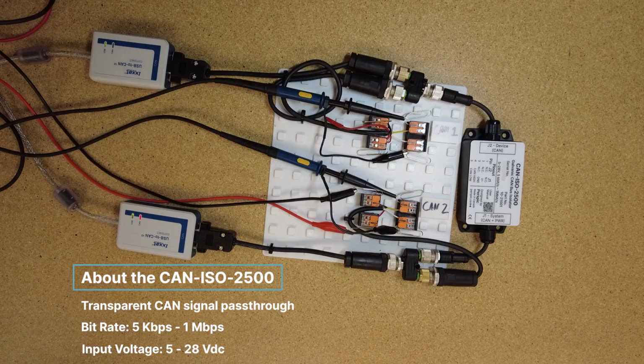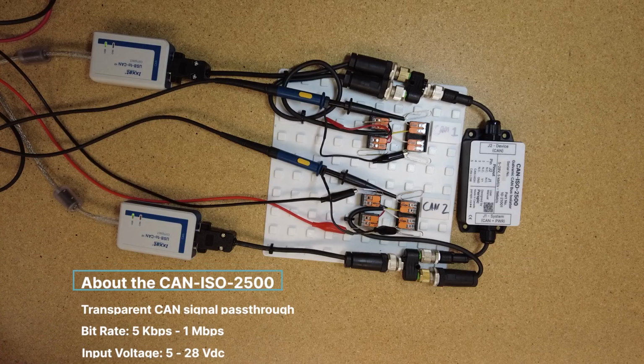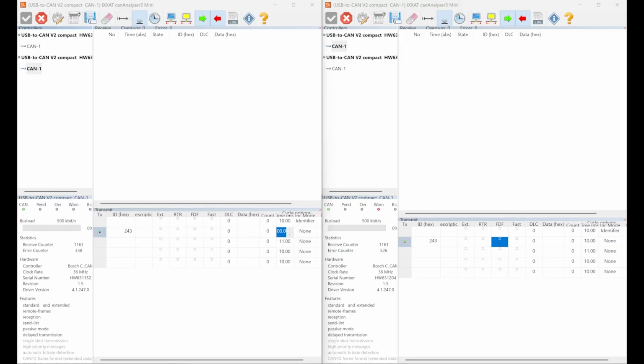For the first demonstration, we're going to pass some data from CAN 1 to CAN 2 and see what it looks like on the oscilloscope. So let's jump over to the computer. Okay, so here we are on the PC. We've got two CAN Analyzer 3 mini windows up here. Each of these is mapped to one of the USB to CAN devices shown in the last clip there. And so we'll start sending some data here.